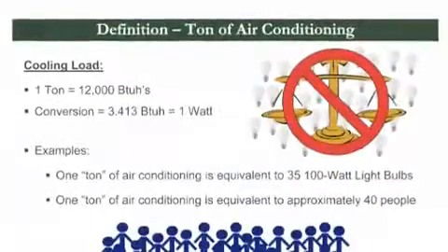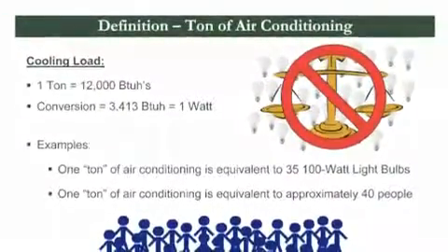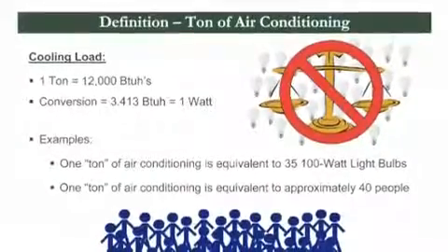When you talk about tons in HVAC, it has nothing to do with weight. It has to do with cooling capacity. There's a little equation, and the only thing you need to know is that 1 ton is 12,000 BTUs and a watt is 3.4 BTUs.